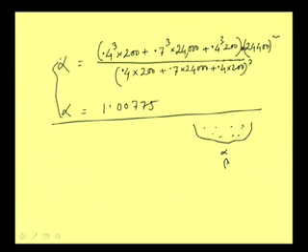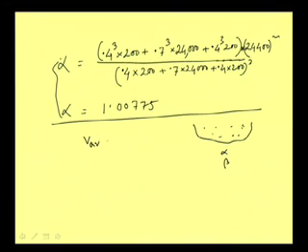Now, in the calculation of average velocity itself, do we need any coefficient? Using the average velocity we are calculating discharge, Q is equal to average velocity into area. Or when we talk about mass, mass will be equal to rho into V average into area. Now, for calculation of energy we are using a coefficient alpha, for calculation of momentum we are using a coefficient beta.